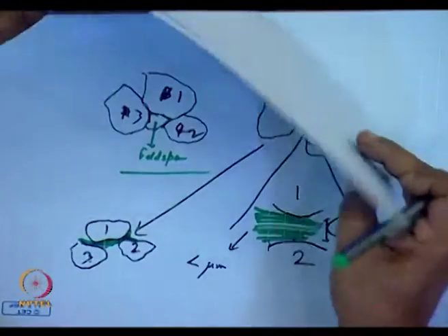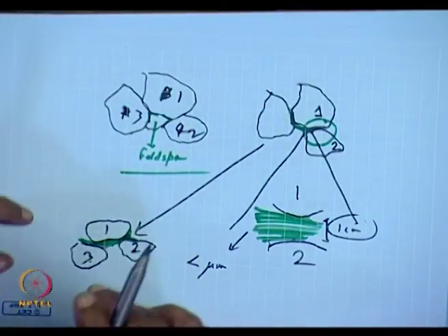Now, I had drawn this diagram and given you a brief hint: the feldspar melts, it forms a low melting liquid, it migrates to the alumina grains, to the silica grains, to the kaolin. This feldspathic melt reacts with them, forming a liquid phase which is now richer in silica and alumina.